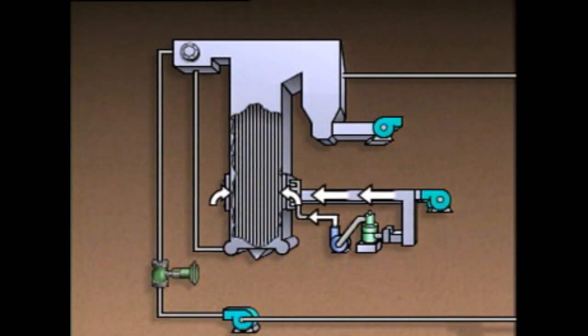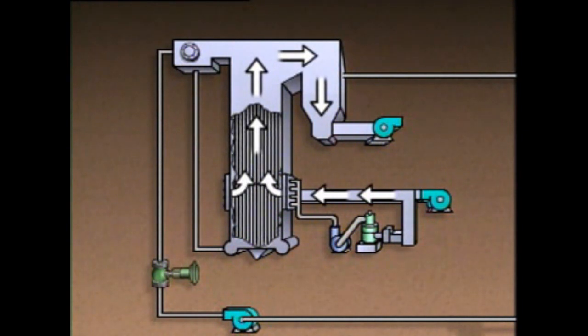After it has been determined that a boiler flameout has occurred, the next step is to put the plant in a safe condition. The real danger with the flameout is that a combustible mixture of fuel and air can collect in the boiler, because fuel and combustion air are still being fed into the furnace. If the operator simply relights the burners, the boiler could explode. In this case, to make the plant safe, you must first stop the flow of fuel into the boiler. Then you have to get rid of all the unburned fuel before relighting the burners. This is done by using the airflow through the furnace to blow the fuel out, an operation called purging.